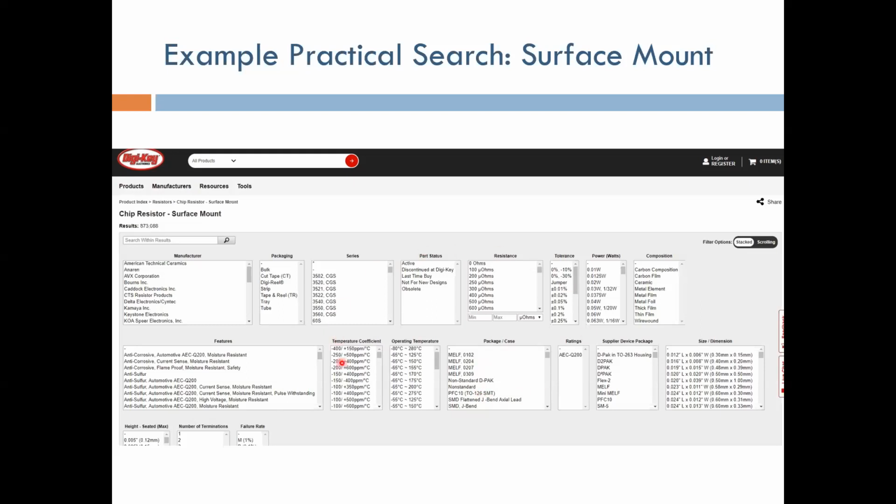You can also choose the temperature coefficient, the operating temperature range, and the packaging, where packaging means how you are going to get your components. Bulk means that you get your components as discrete components, each one separate from the other. Tape means that the components are connected with an adhesive to a tape. This is usually what an assembly machine uses. Tape and reel is exactly the kind of components that automated assembly lines use. You put the tape in its place, and the machine takes the resistances one by one and attaches them to the place on the printed circuit board that you want.